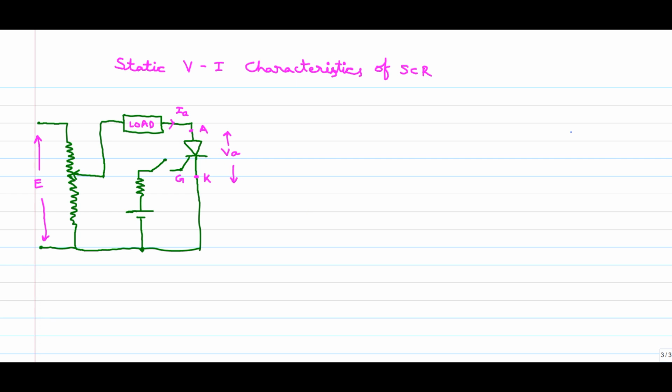Yes, so this is the diagram, how to draw it. And I can call this EG, the voltage for the gate, and this is RG, the resistance for the gate terminal. Through this EG and RG, we are providing the current to the gate to cathode. By providing gate to cathode voltage, we get current passing through that inner P layer. So this is the concept. Now we will discuss how to draw the VI characteristics.